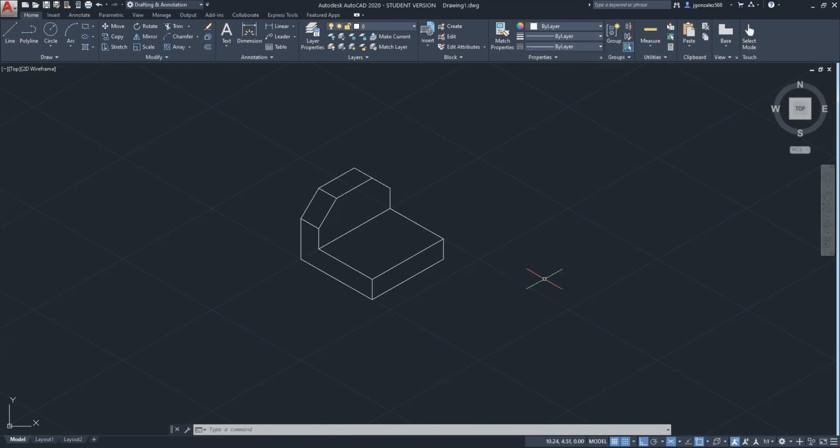So once you've done that, we're going to open up the ellipse command. We just type EL, choose ellipse right there. I believe it's probably also under draw, or I forget where, but I prefer to type it myself. So type EL, enter to open the ellipse command. On the bottom, choose ISO circle. ISO circle will create circles based on which plane you're looking at.